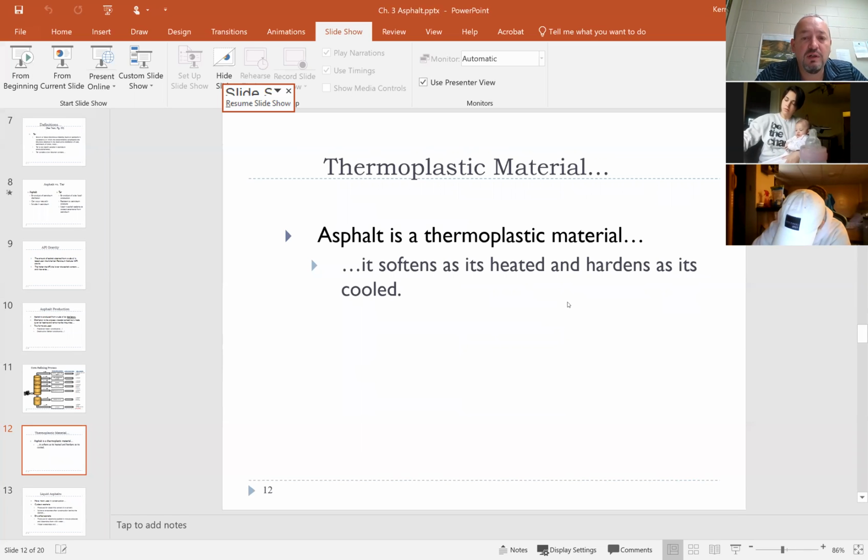We're going to spend one whole set of slides and handouts that I have on pavement distresses, and they distress in totally different ways, because asphalt is not only flexible, but, why I thought of that on this slide, it's a thermoplastic material. So as it gets heated, it softens, and of course, as it gets really cold, you could say it gets very brittle. And so, if we don't design the asphalt properly with respect to air voids and the right type of asphalt and the right mix, we could have problems both ways.